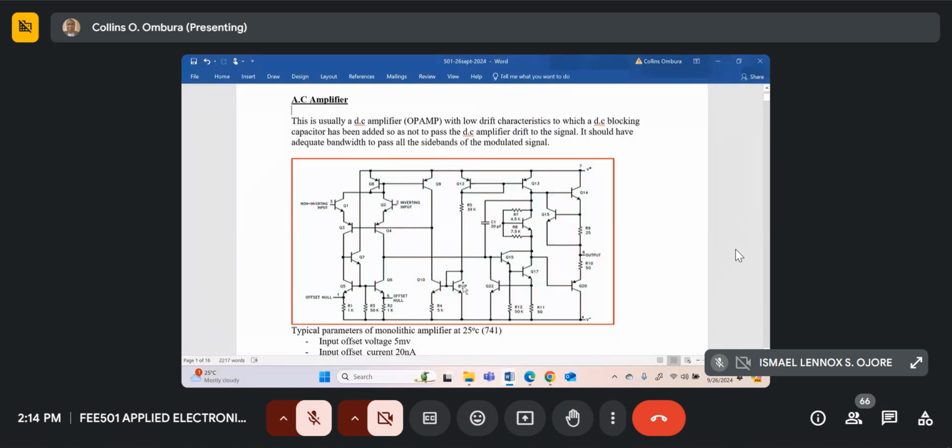This is actually just for biasing, just for biasing using current mirrors. So just a biasing circuit. And then Q15, Q16 is the Darlington for the second stage, which has an active load. The load is actually Q13, and the inputs to Q14 and Q20, which are actually the class B output stage. Q15 we said was just for protection.